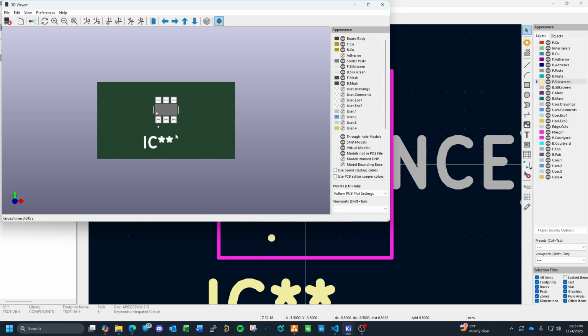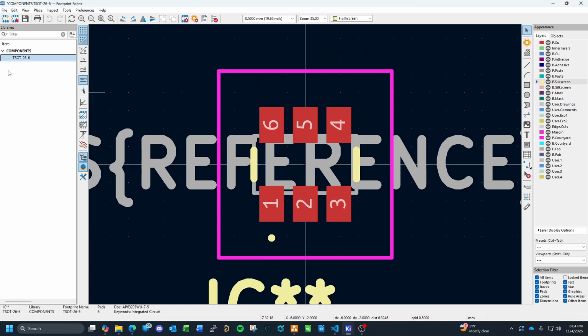These are great. I know in Altium and CircuitStudio, you can export a step file of the PCB with the components placed. That's really great if you're working with a mechanical design house that's designing an enclosure for you, so they can test fit the board into an existing design using something like SolidWorks or Fusion. That way we don't have to keep recreating a footprint over and over again. It saves a lot of time. So we'll save that.